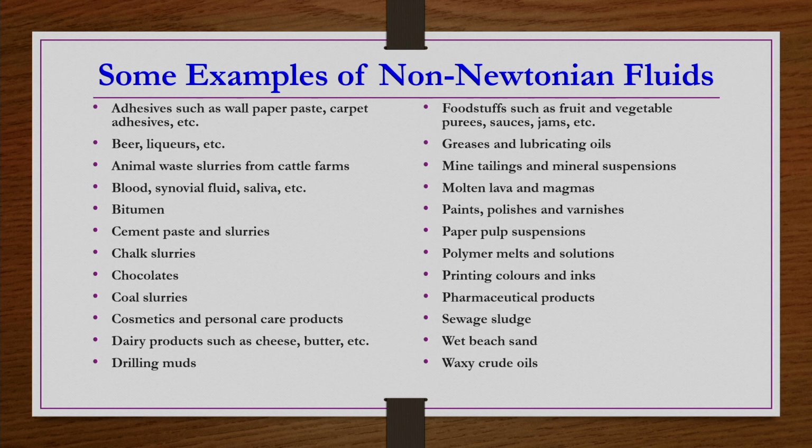Remember, I will be recapitulating this several times in at least the initial 2 to 3 weeks. Whenever you talk about non-Newtonian fluids, you should ask what is the range of gamma dot, the range of shear rate, because soon you are going to find out that under a certain range of gamma dot the material may have one characteristic, in another range it may have different characteristics, and in the range of a large shear rate it may have entirely different characteristics.